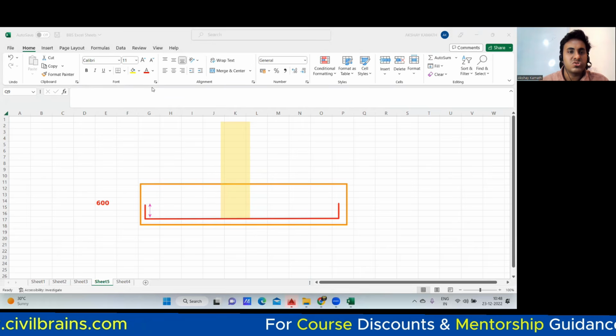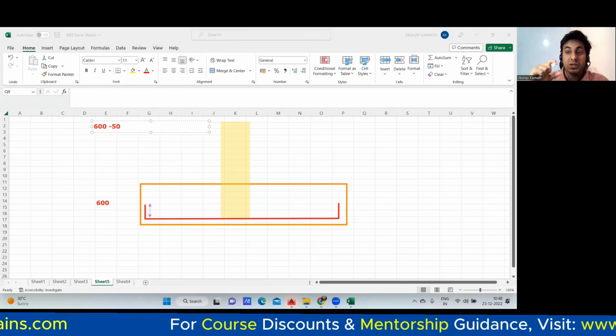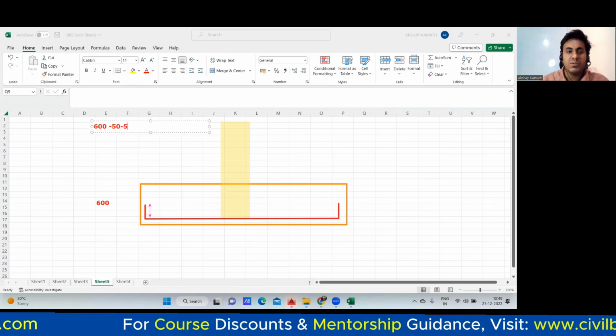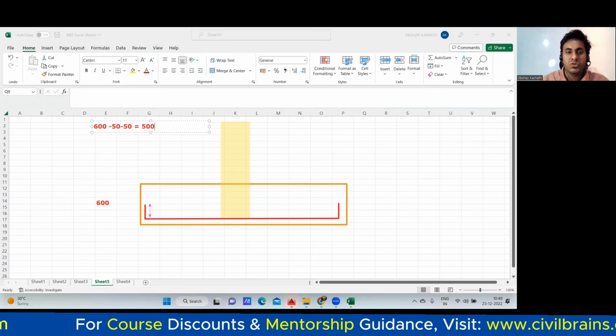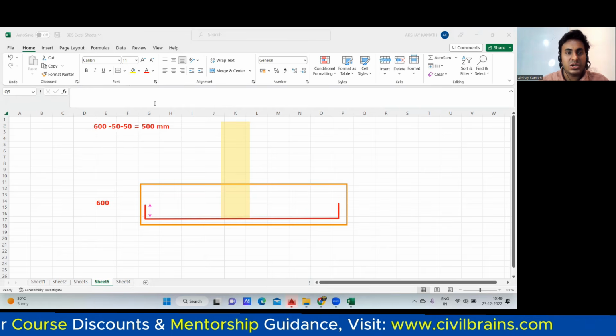The usual formula we apply: overall depth minus, from the top, the 50 mm cover, and from the bottom minus 50 mm. So it will be 500 mm. That means this particular L will be 500.